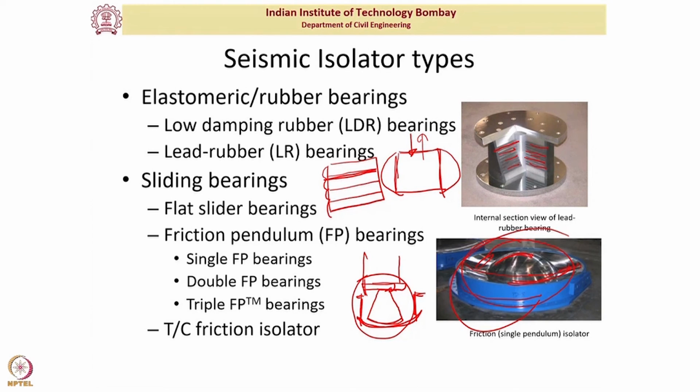Elastomeric bearings have other kinds of issues, like you have ingress issues in the sliding bearings, or change in the coefficient of friction. The problem with rubber is that over time, the property of the rubber actually changes. It changes because of environmental conditions, like sunlight, or because rubber is a material that keeps on getting cured over a long amount of time.